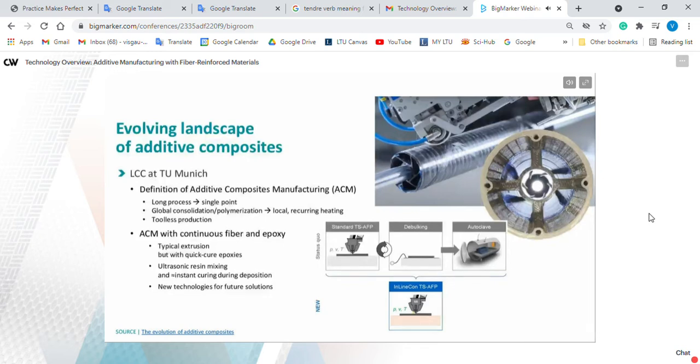And as you see on this cross-section of this drive shaft, they've not only printed the end fitting with the material, the fastener inserts, but as you look down the cylinder, you can see this kind of spiral. Well, those are longerons. Those are longitudinal stiffeners that actually spiral as you go to the other end. So we have this whole new way to think about how we design structures and how we can achieve those.